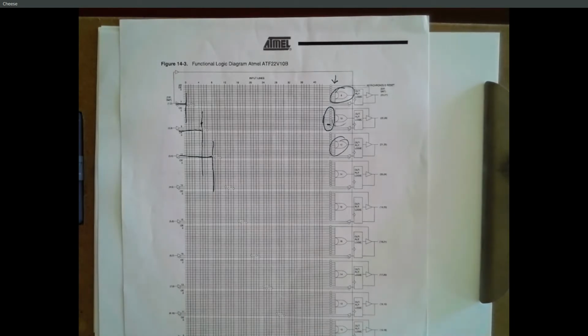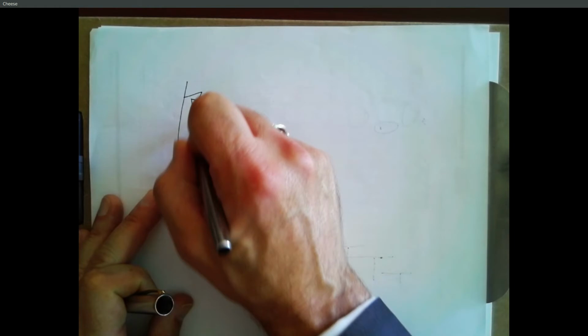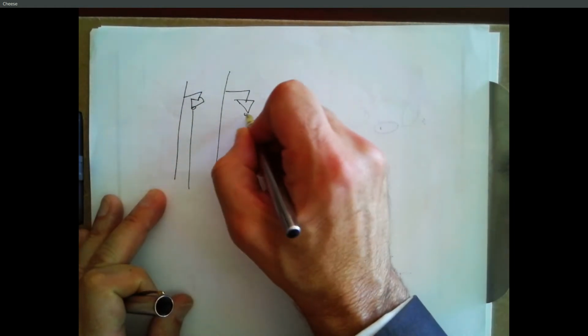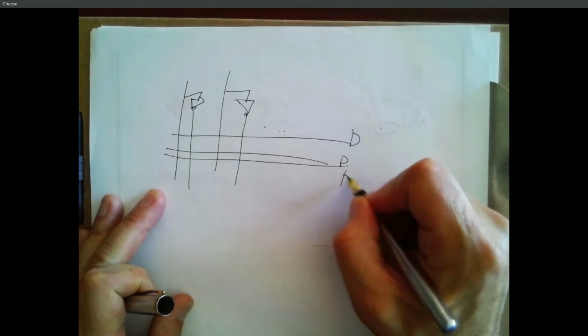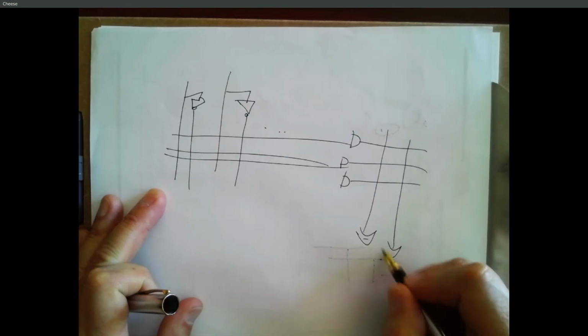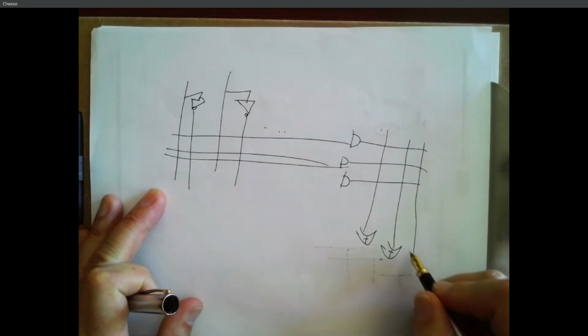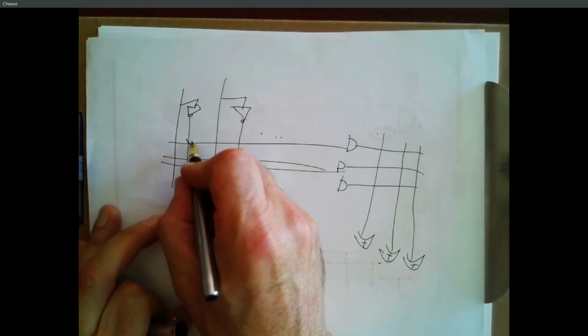But the fuse maps that you've seen on homeworks or on the midterm, that's as complex as we need to go. So mostly it's just inputs with inverters and so on, AND gates, and then OR gates. And when you want to show a connection, we typically just draw an X.